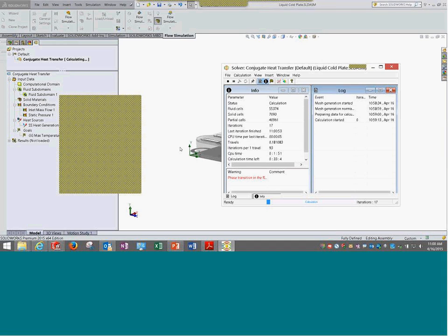If I remember, one of the next chapters is more towards the time to reach a particular step. Okay. Now, if I put the answer in a different way, obviously the goal is required. I also want to plot the goal versus time plot, and when it becomes flat, we know it has reached a steady state. But it cannot stop automatically. What we can control is only through the calculation control options. Those are the only options that we have in our hand to stop the solution.